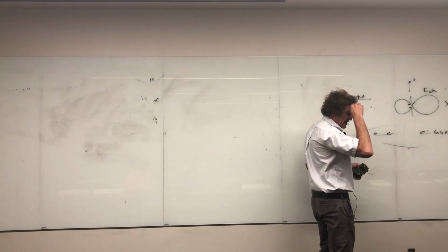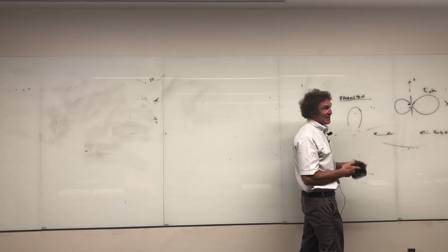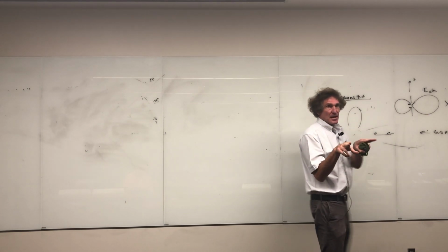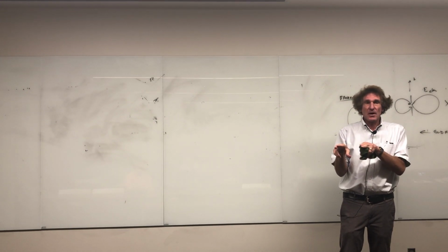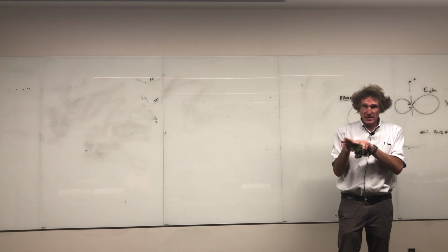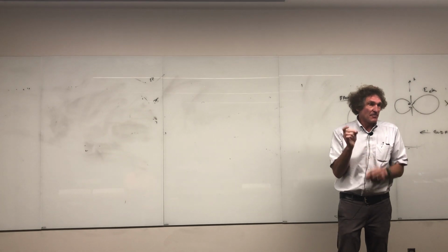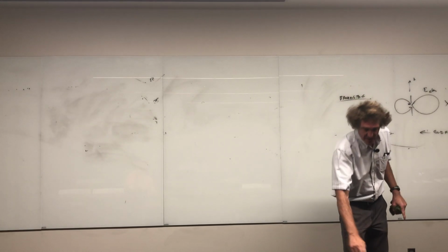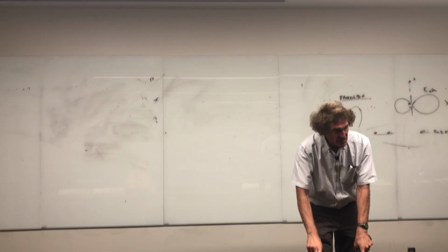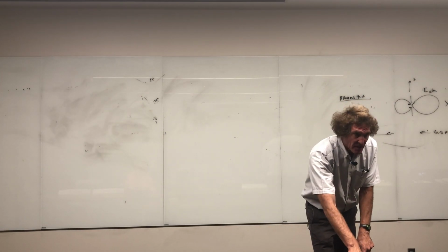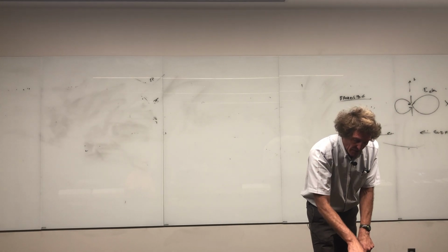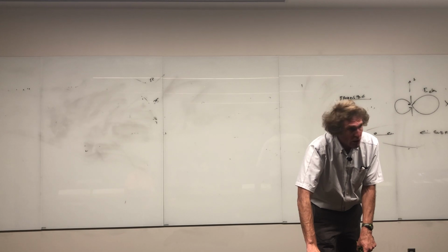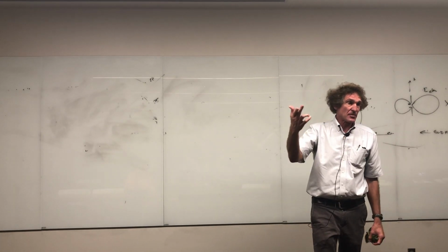Yeah. Well, there's a lot of ways. You can do it literally. If you think about this, when you have a signal coming out, right? First, if you're talking about just you have the same input impedance. If you want a different phase, well, phase has to do with what? The length of line that a signal travels. So if I have two antennas, and I want this one 90 degrees different from this one, I have a signal here, right? I come out, and now I make the length of line on this one longer by 90 degrees or longer by pi over 2 radians.